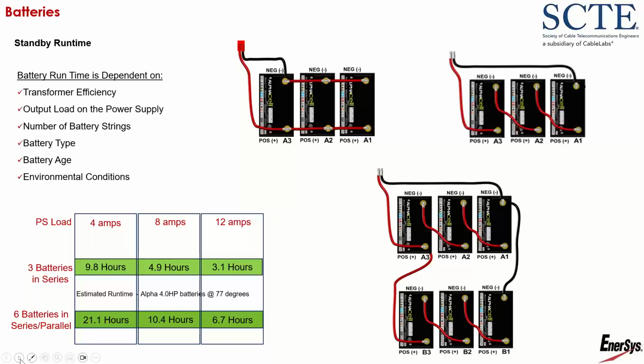On some of the older power supplies, or maybe not, I shouldn't say older. We have a power supply called an XM2, and that XM2 has a transponder called a DM3X. Most of the transponders on power supplies, the modem is actually powered through the interface between the inverter and the transponder. On that particular transponder, the DM3X, we actually power it with the little sense harness wires that come from the batteries.